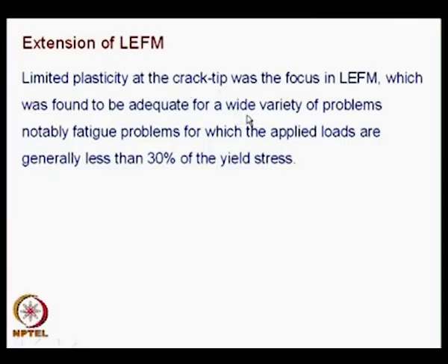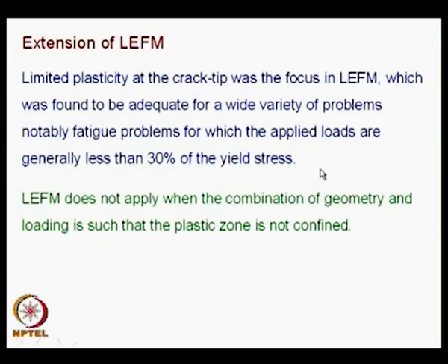As design requirements expanded, this kind of analysis was not found to be sufficient. So, when you have a different combination of geometry and loading, it could lead to expansion of the plastic zone. So, the plastic zone is not confined. So, in such applications, linear elastic fracture mechanics would not be sufficient. So, you have to look for newer methodologies,